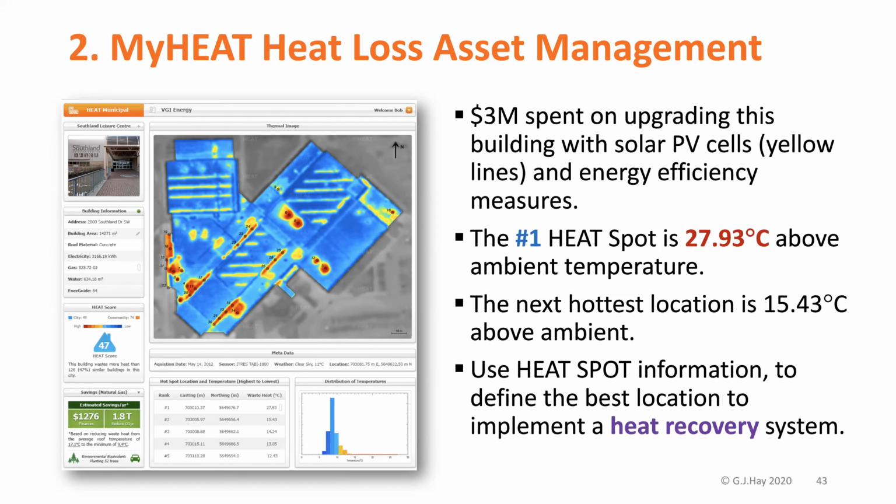But instead, if you could take your cold air and pass it over a heat recovery system, where hot air leaving your building warms up the cold air. So let's say it's minus 30, it goes over the heat recovery system, and now it brings it up to, let's say, 2 degrees or 1 degree. Now you only have to heat from 1 degree to 21 degrees instead of from minus 30 to 21 degrees.